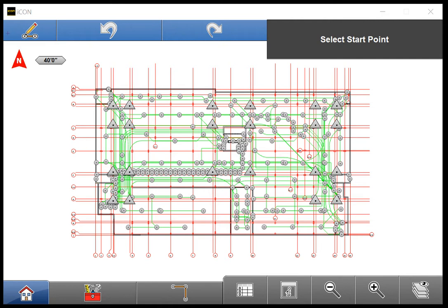The purpose of the sketching application is the creation of points and lines in the field as needed. The most common use in our line of work is the creation of control offsets when we only have one intersection of control lines on a deck, or when our other intersections are covered. A similar but less common use is the creation of a point for layout because of field conditions and ensuring that the point is located properly. Both uses will be covered in this video.